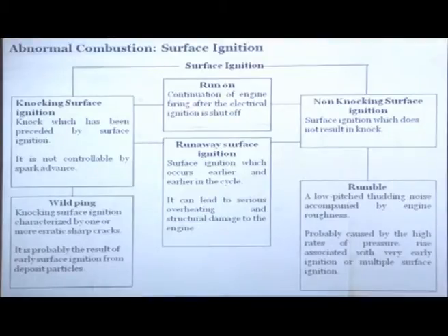There is something in between, that is called run-on: continuation of the engine firing after the electrical ignition is shut off. If the electrical ignition is shut off, it will cut the current to the spark plug. But if there is a surface which is hot, the engine will not stop and will continue to run. So this is called run-on.